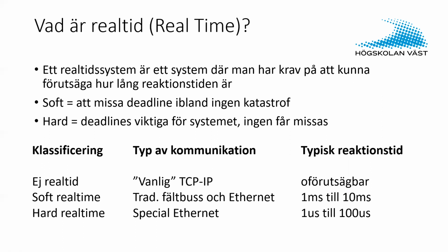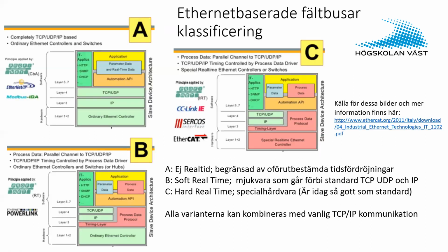But when you look at Ethernet, they have a classification that's quite interesting, I think. Many try to adopt Ethernet hardware because it's cheap and existing. And you could then classify different things according to non-real time, soft real time, or hard real time, A, B, C. If you do no real time at all, you can use standard hardware, standard internet protocols, TCP/IP.